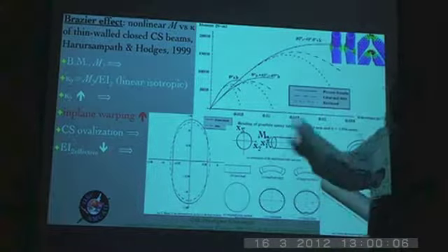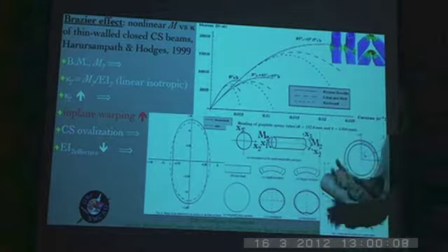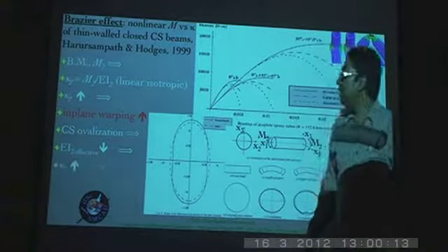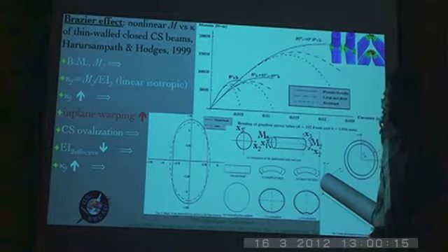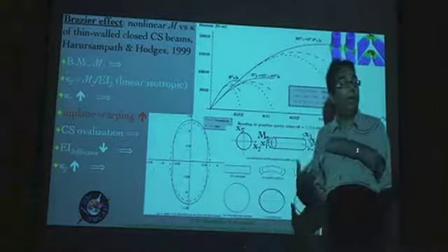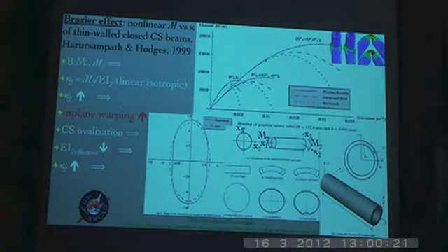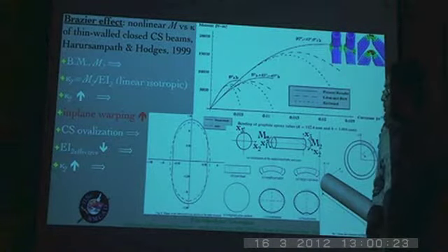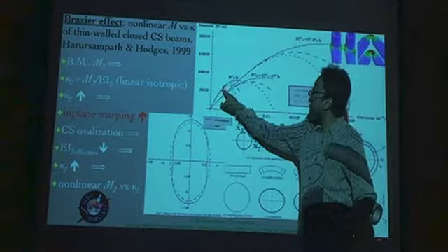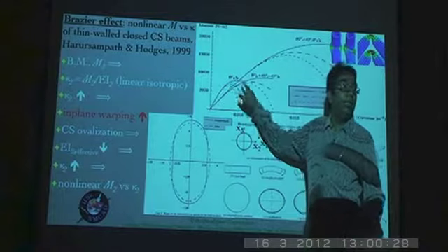In the 1D analysis, what is of significance is that the bending stiffness EI2 effectively reduces, which means that the curvature is much more than expected out of a linear model, which in turn means that M2 versus kappa 2 is no longer a straight line; it takes a non-linear behavior.